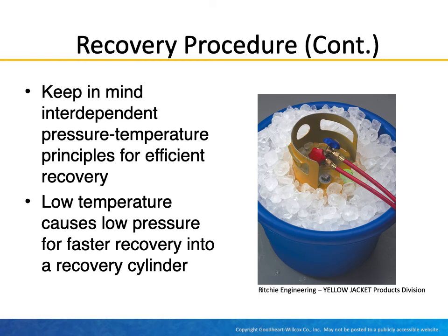Keep in mind interdependent pressure temperature principles for efficient recovery. Low temperature causes low pressure for faster recovery into a recovery cylinder.